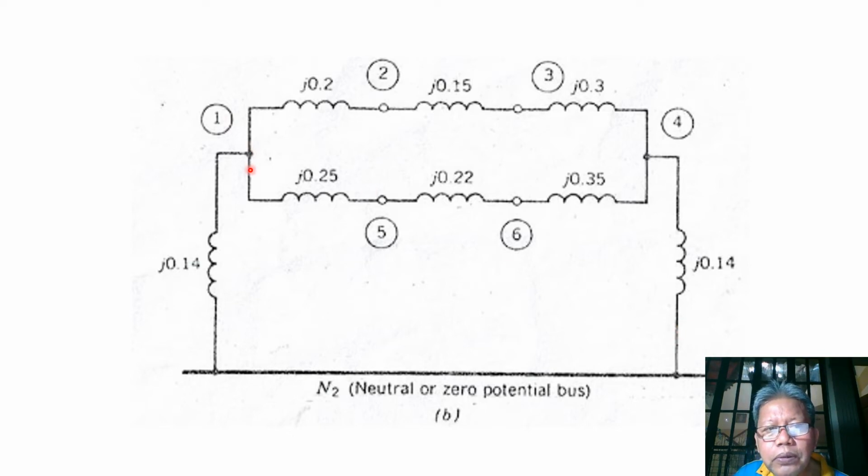Now, down below, from bus 1 to bus 5, we have transformer 3 with reactance of J0.25. And again, a negative sequence current can flow between bus 1 to bus 5. And then between bus 5 and bus 6, we have a transmission line which can allow the flow of negative sequence current.